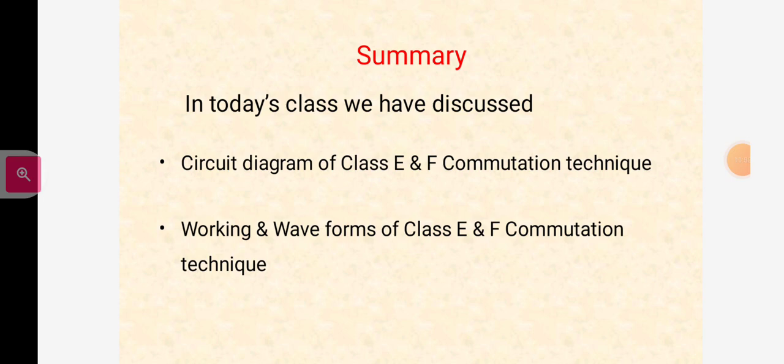Power control in metallurgical process using electrothermal process such as electric arc melting, arc welding, induction heating and melting, resistance heating, etc. Power control in chemical processing using electrochemical process such as electrolysis, active power filters and reactive power compensators in power system, high voltage supplies for X-ray generators used in X-ray machines, high voltage supplies for electrostatic precipitators used in chimneys to separate suspended particles from flue gases to control the pollution.